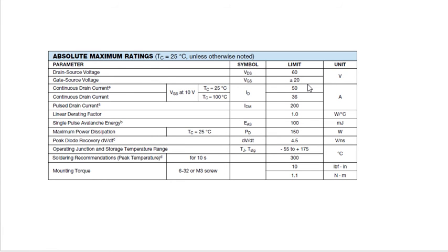And one more thing, when you see the curves in this datasheet, one axis represents the drain current, and the other side you will have the different gate to source voltages. At a particular gate to source voltage, you will be able to get a particular current capacity of that MOSFET. So by that also you can finalize the VGS.